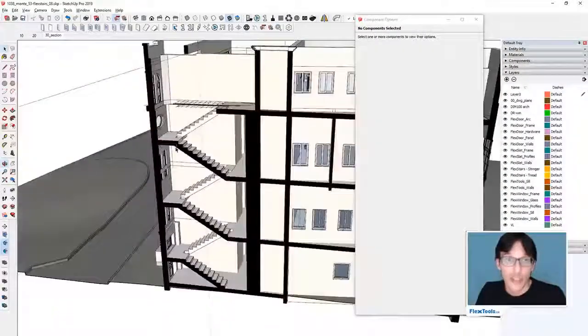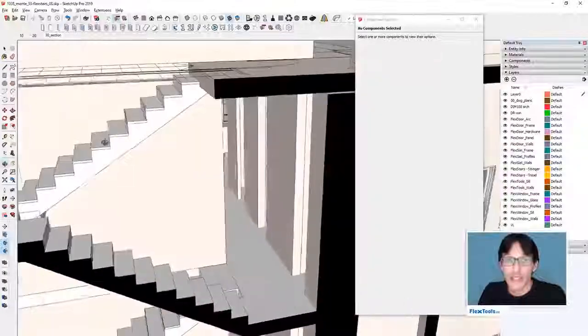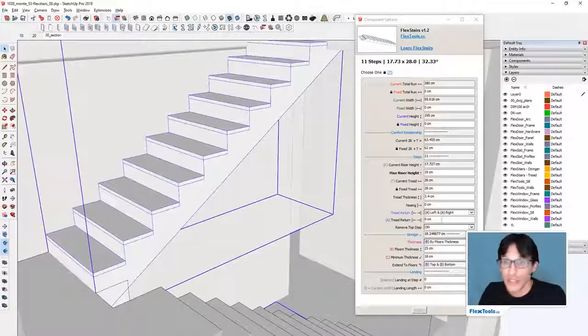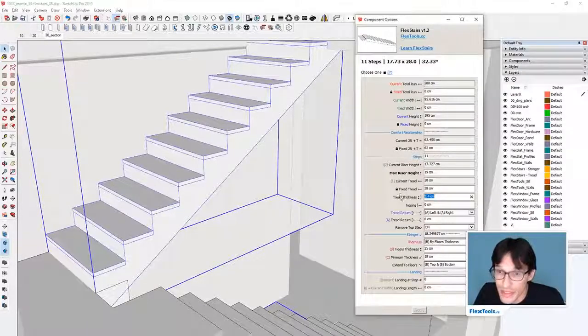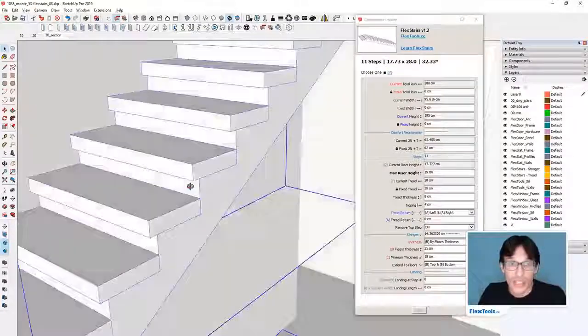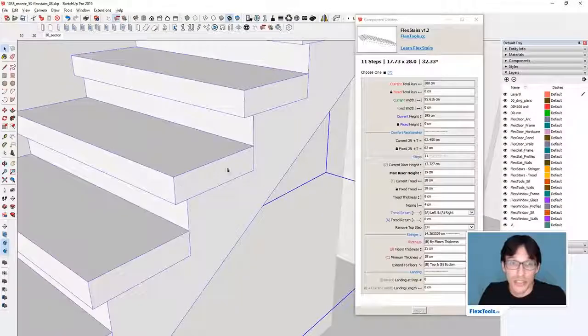Yeah, that's pretty good. Now another nice setting we have for the stairs is you can play with the tread like we played before. You can change the thickness of the treads. Where's the tread thickness? Right now it's 3.4. We'll change it to 8, for example. So you'll see everything became 8. You can pull the nosing out 4 centimeters. The nosing came out. We can also change the tread returns. Tread returns are the side part of the stairs. Right now the tread return is at 0. Let's say we'll also do 4.